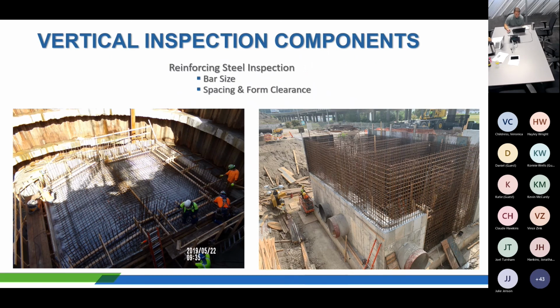Structural work. So a lot of these jobs do involve concrete work as well. Unless the specs call out something specific for third-party testing, in most cases it's the RPRs that are looking at the rebar on this. So, getting yourself familiar with the structural drawings, the rebar shop drawings, and the contract drawings, and understanding what those say.